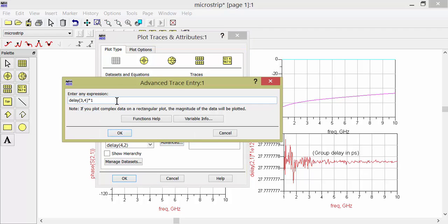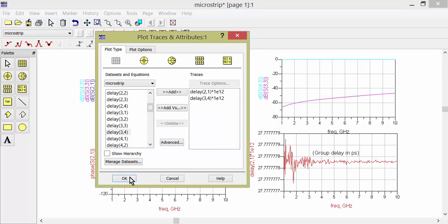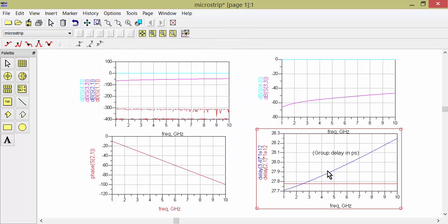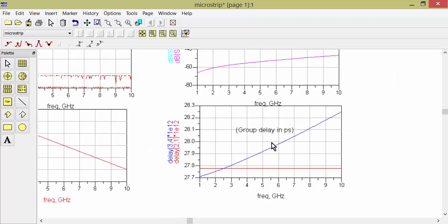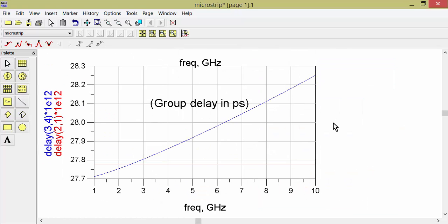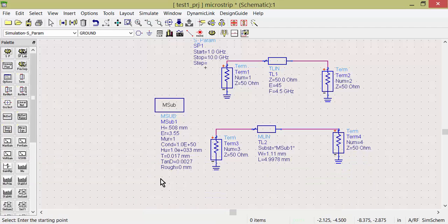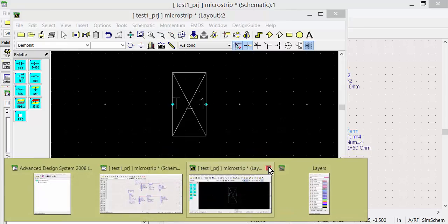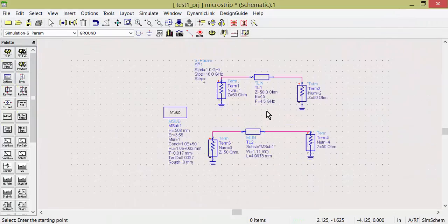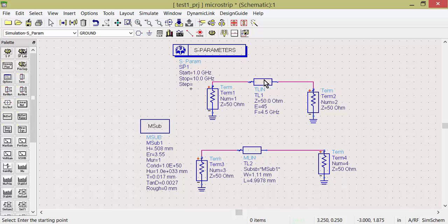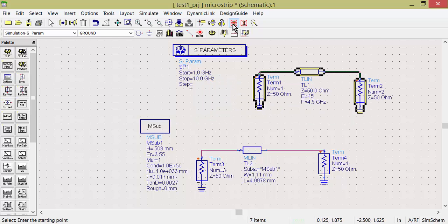For that, I am just disabling this part. So in momentum, actually I will do this model. Actually I have to import it. So first go to general layout. Automatically it will take the layout, whatever I am giving. So this transmission line is coming, with width and length as usual from the schematic, whatever I have in the schematic. Now I am giving a port here.